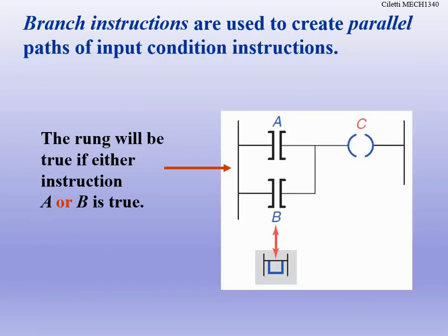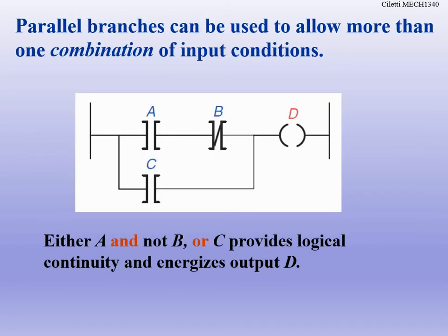Okay, when we start doing branching instructions, remember from a previous lecture, this is how we OR something. ORing is branching. So A or B will turn on C. Essentially, that's what you're doing. Now, what they show at the top here, that's how Siemens will probably look. What's on the bottom is how Allen Bradley might look when we go through this. But there's different ways to branch. So ours isn't going to look 100% like this in our Siemens software, but it's still the same concept.